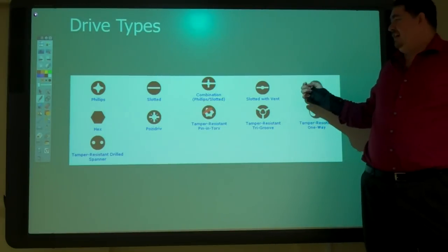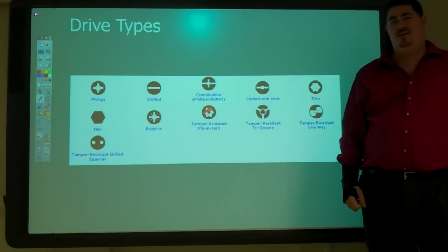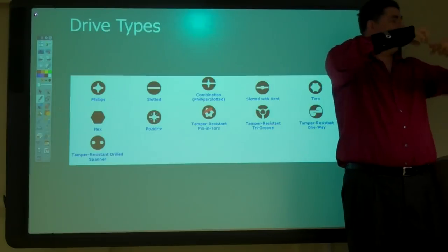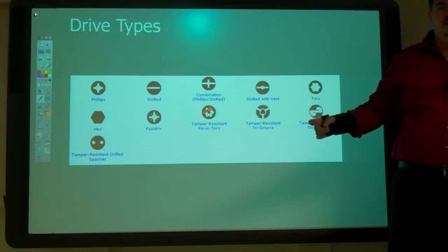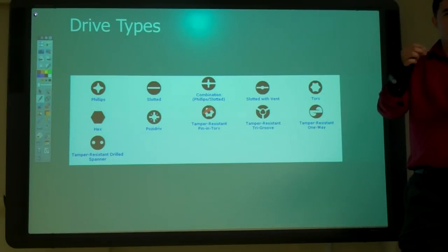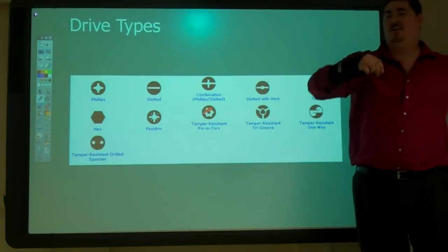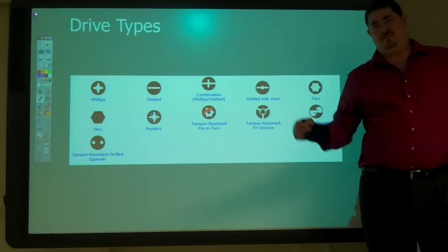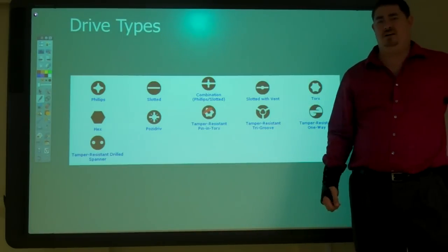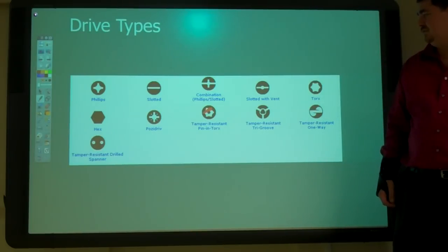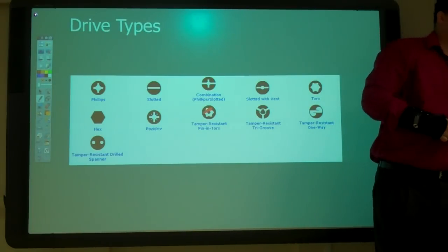Why do you think I pay the extra money for a Torx rather than a Phillips? Because Phillips just twist out, spin out, strip. Yeah, Phillips can strip out, and with the shape of the Phillips, it can go out here straight on. Although here, it's not going to fall off the screwdriver. I can put it on the screwdriver and move it around as long as I don't point it down at all. The screw is going to stay on the end of the bit. I can adjust it and change whatever angle I need to, and it'll stay on there and go through. It's not going to get lost, even without a magnetic tip.